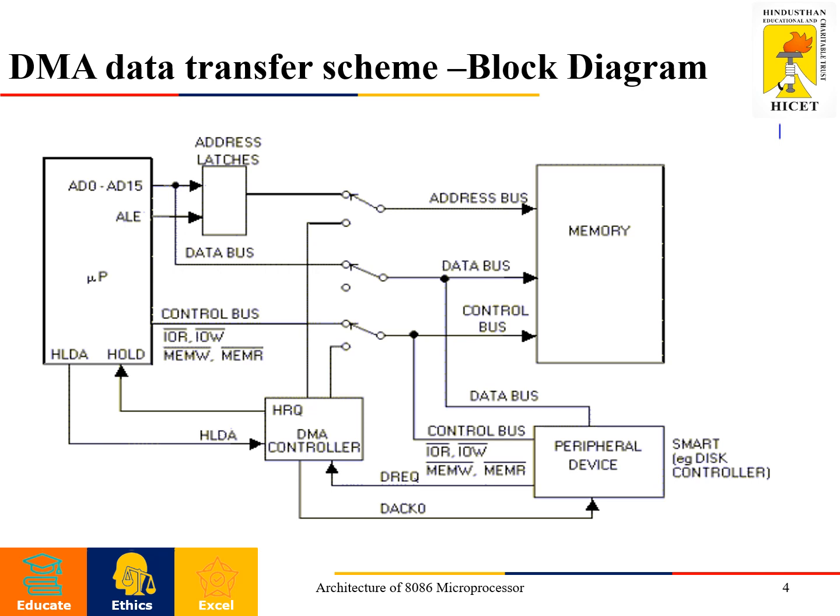Once this acknowledgement is received, the microprocessor will automatically go into sleep mode and transfer the bus control to the DMA controller. Now after receiving control of the buses, the DMA will directly transfer the data from memory to memory, or to these external devices.